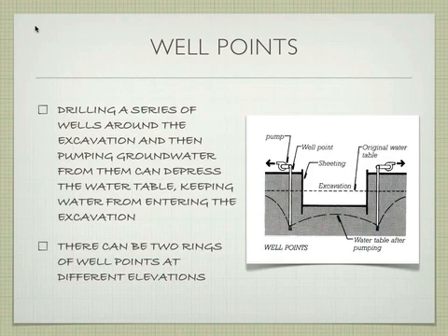Yeah. When would the pumping actually be occurring? I mean, you wouldn't leave it running throughout the whole excavation period. You would leave it running during the whole excavation period until you poured your foundation with some kind of a waterproof barrier, that keeps the water out of whatever that is.